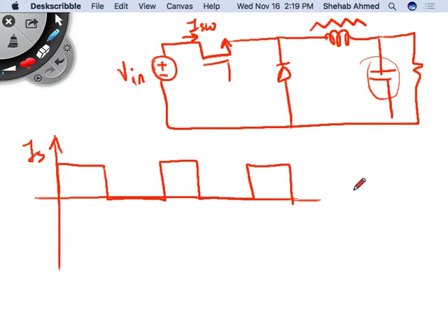The battery will then be modeled as an impedance in series with a DC source. And here you will have an effect of the inductance of the wires, and it's a bigger mess, which will affect your transient response. So batteries don't like that, and their lifetime will be reduced if you do it this way. So how do you treat this? If we look at this current, and consider some inductance and some resistance or impedance here, what is this going to cause to the voltage at the input? It will also have ripple.